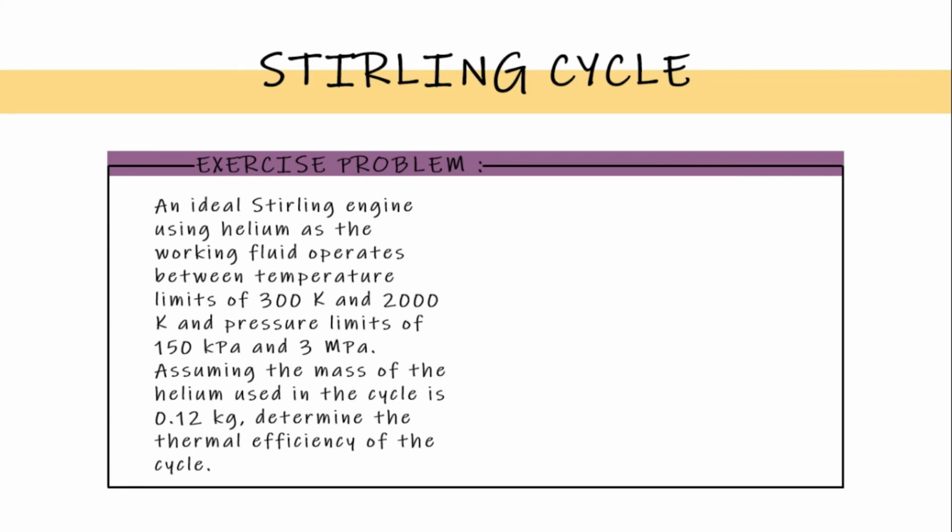Now, that's the end of our example problem. So, my last tip for you is that you don't need to specifically follow the order of solving, like point 1, then point 2, after the cycle points you head for the cycle performances, and last MEP. No, it always depends on the given, so analyze the problem carefully. And always remember the diagram. Always draw it up before answering questions like this to prevent confusion. It's always the key to understanding thermodynamic cycles more in depth, or more proficiently.